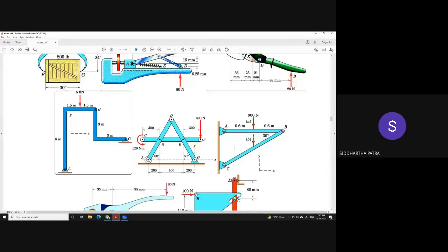Rightmost, okay. Sir, if I think of the part BC as a rigid body, then to have equilibrium, the same and opposite force should apply at point B and C along the line BC. Then, sir, I can take the vector F that is applying at point C, and think that AX and AY is acting at point A. Then the variables will become 3.